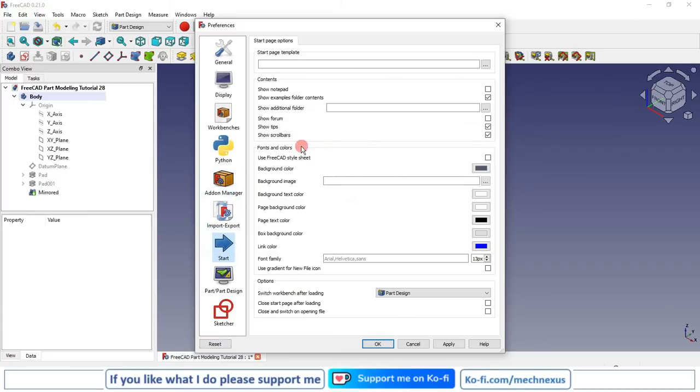On start page, when you start the FreeCAD, then you can set your default workbench. For example, I use the Part Design workbench a lot for part modeling, so I want that whenever I restart the FreeCAD, then the Part Design workbench should load by default. So here you can set your default workbench.